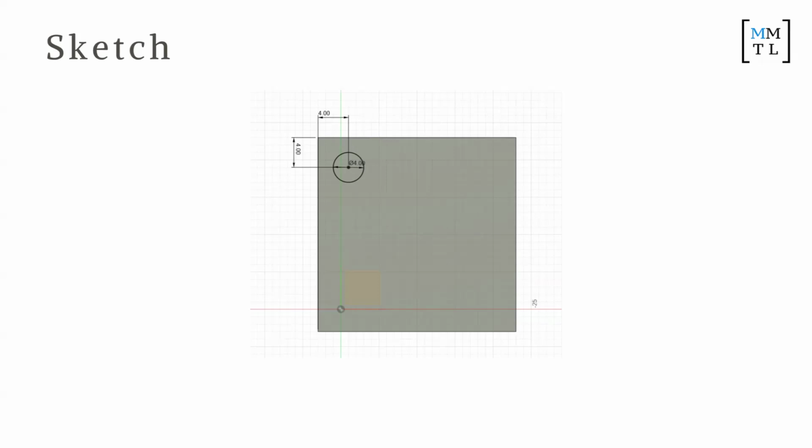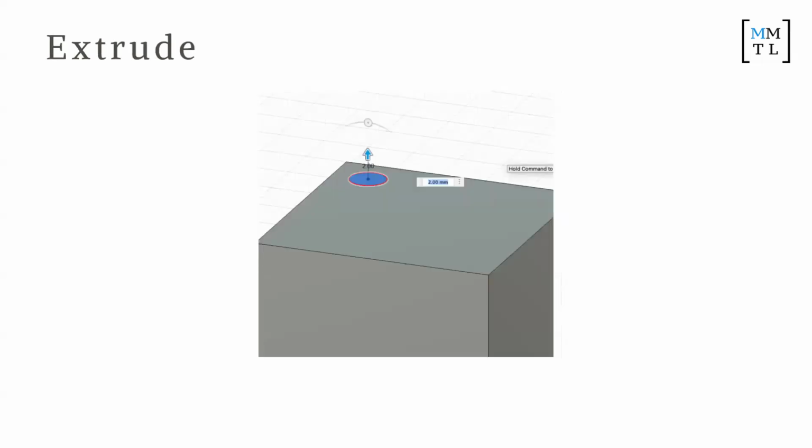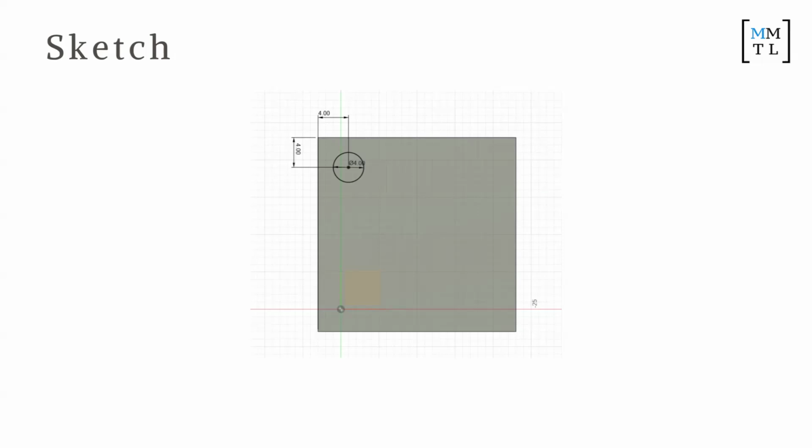Oh, are you still practicing the offset? No, I was just trying to create a new plane to place the circular sketch. We don't need to create a new plane because we're sketching on the body of the cube. Yeah, you can do it on the top surface. We are extruding it, so yeah, we're going to extrude this.